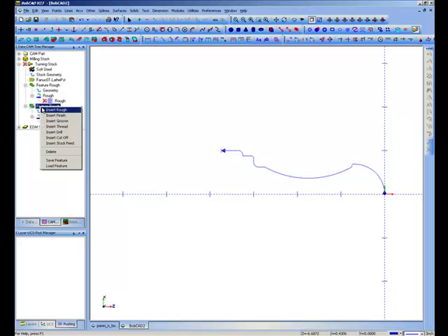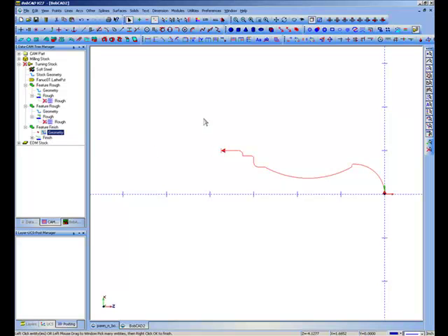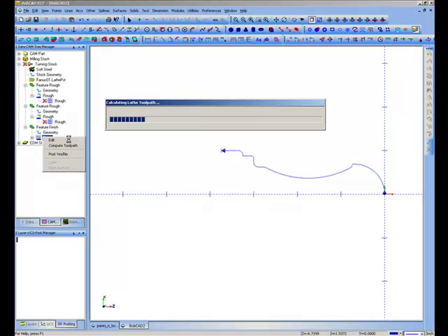And then let's go ahead and finish it off. And essentially, I'm going to just do the same thing for the finish pass, just because I don't know any other way. But I can put a finish one on with default tooling. I mean, who knows? 0.1 I think is that it's leaving a 0.1 depth or something. So who knows what I'm really cutting? But there's a finish tool that way.